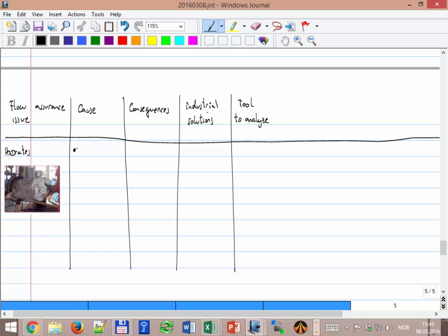You need water. Does it have to be liquid, or can it be vapor? It has to be free water, liquid. If you have water that is just vaporizing in the gas, there is no issue. But when there is condensation, when the water comes down, then you might have hydrate problems. So you need to have free water.